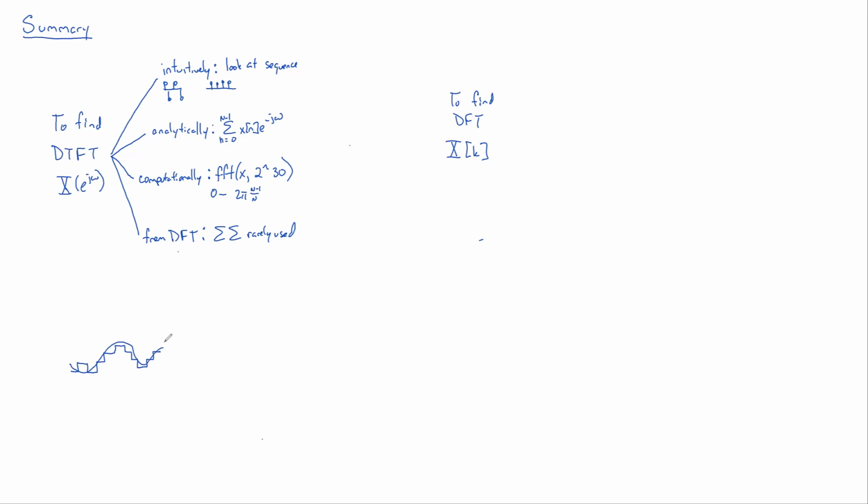If this was your signal into the motor of a robot, that robot arm and that motor has inertia, and it's not going to instantly move in jagged leaps. If it's being sampled finely enough, the inertia will just make it smoothly interpolate. So you actually rarely need to perfectly reconstruct something in a very smooth domain if you've got it sampled finely enough.